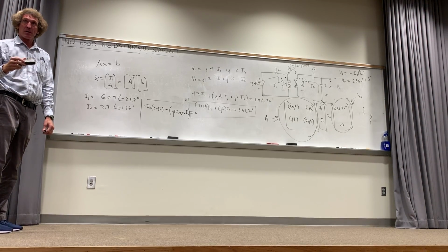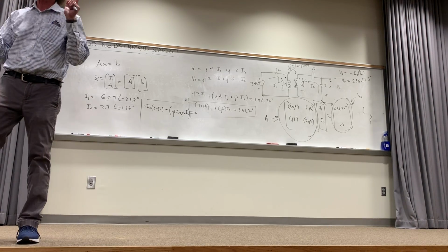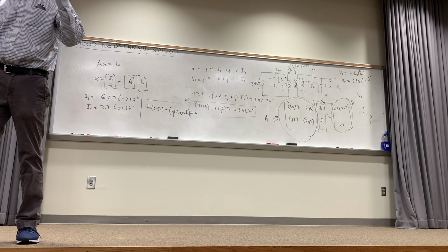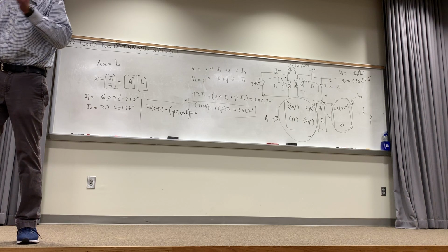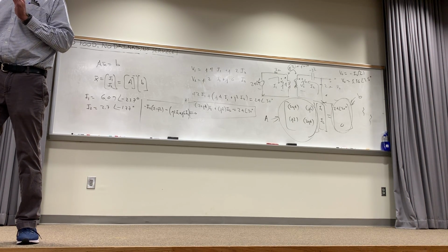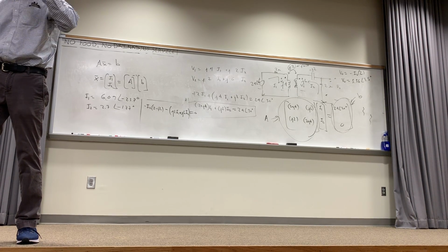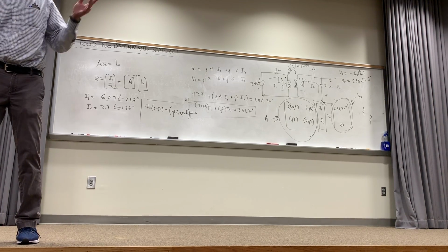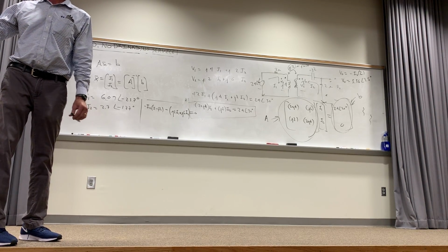So we're solving for V naught. That's what the problem asks for. You need the currents to get that though. No matter what they ask, the fundamental things you go for are I1 and I2. With mesh analysis, regardless of what was asked, you solve for I1, I2. With nodal analysis, you want to find the node voltages. This is like mesh analysis. You need the currents to get any other information. The 2 is just the resistance. They wanted the voltage across that resistor, so we need the value of the resistance. Got it, everyone?